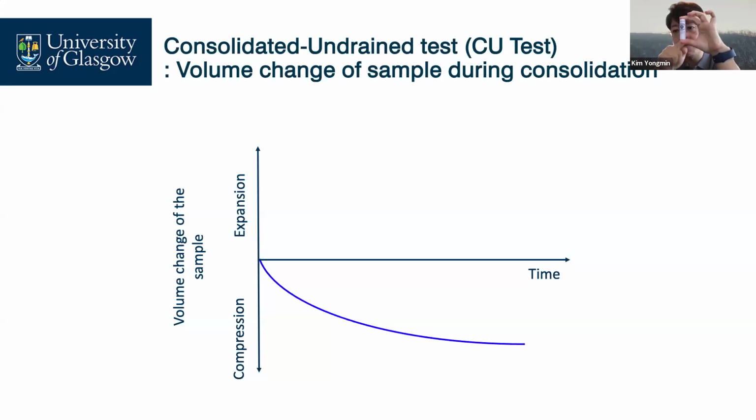Before applying load, we take pictures and then send them to our AI models to capture the volume of soils. And then after compressing our soils, these soils look bulged, right? Then we take a photo. It is a different shape, but we hope that water cannot be drained out. The total volume would be the same, but we have a different soil sample shape.